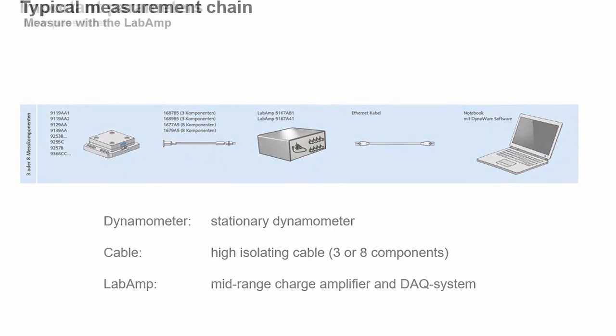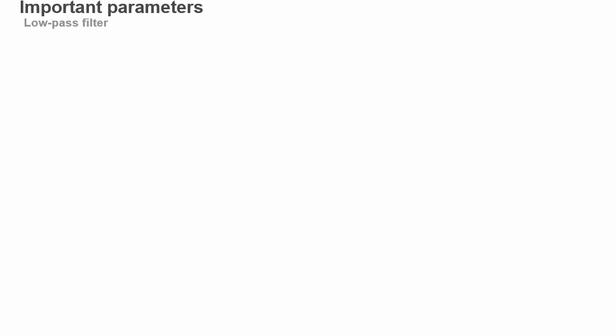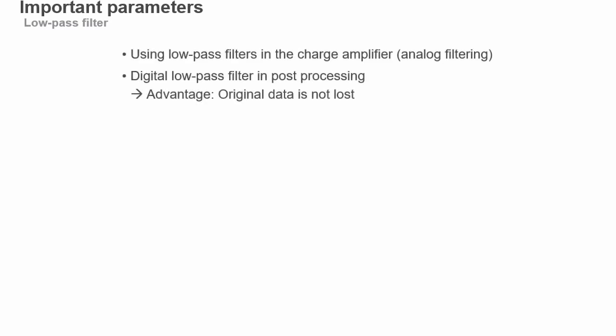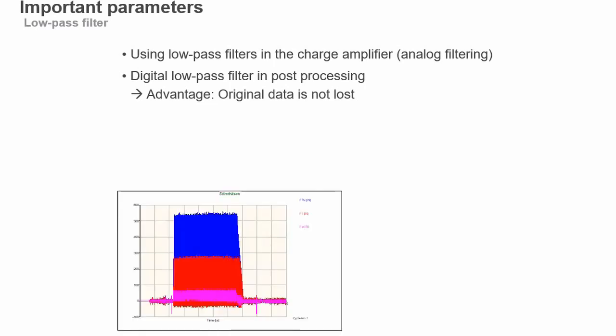Okay, the digital post-processing is a very important part of cutting force measurements. So a low-pass filter allows us to remove noise from the data that we have captured using the sensor. Okay, so it is very essential to use this digital post-processing to present data that is readable.